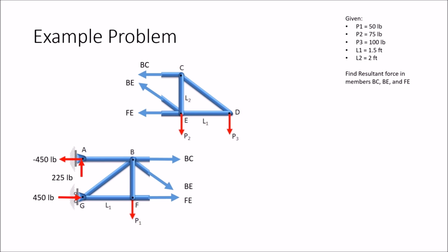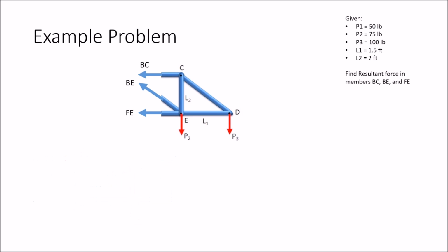I always ask myself, which is easier? I look at the diagram and think that the one with the fewer forces is always easier. Knowing that, I would say that the top one that shows the right half of the structure is easier because it only has 2 forces acting on it, where the left half has 4 forces. Now we can look at finding the sum of the forces in the x and the y directions and take a moment about a specific point.